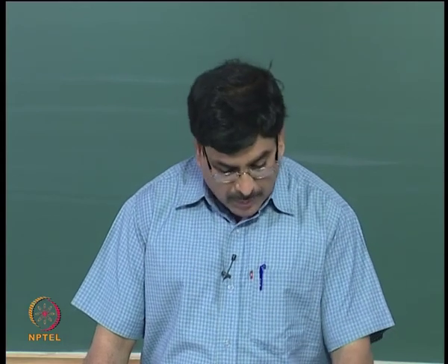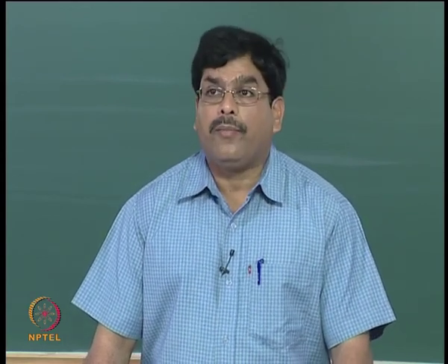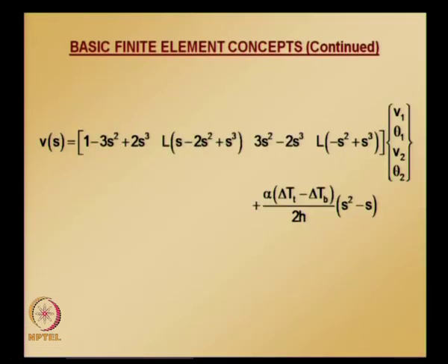So displacement at any point in the element is given by, the first part is nothing but interpolation of nodal values, and the second part is the correction coming from the fixed end solution.